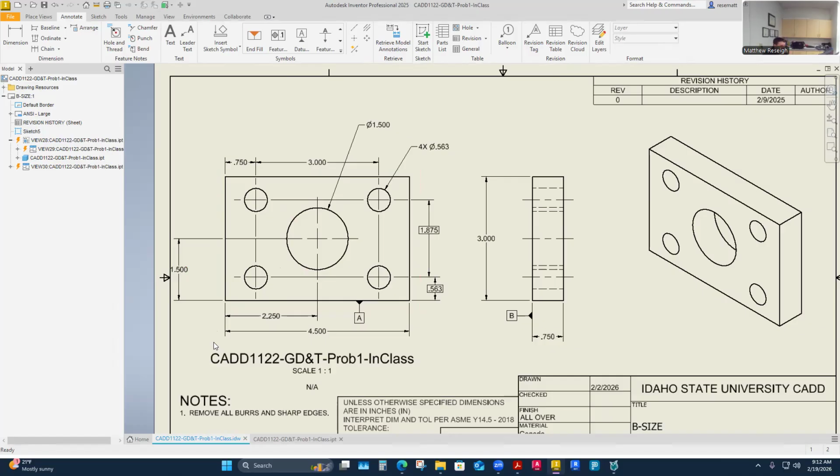That's why, as I entered the GD&T world, I'd say, well, let me just dimension it with my normal CAD skills. Now let me identify which are locating dimensions for features of size, and think, what are the best dimensions to pull? Now let's control where they're pulled from with datums. To me, that's the thought process that's going to help me establish what datum.